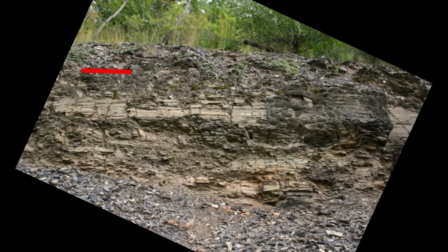And that means, how far is the pile going to penetrate below the top of the bedrock contact, the weathered bedrock contact. Again, this is a still photo from that earlier segment where I showed the pile driving, and it shows the exposed shale surface. Shale is typically highly weathered at the upper portion, and then it grades into harder and harder material with depth. Of course, this is a sedimentary rock, and so you typically have horizontal bedding planes that are visible. And even in the case where the upper profile is pretty much soil, the soil can retain some semblance of that rock structure.